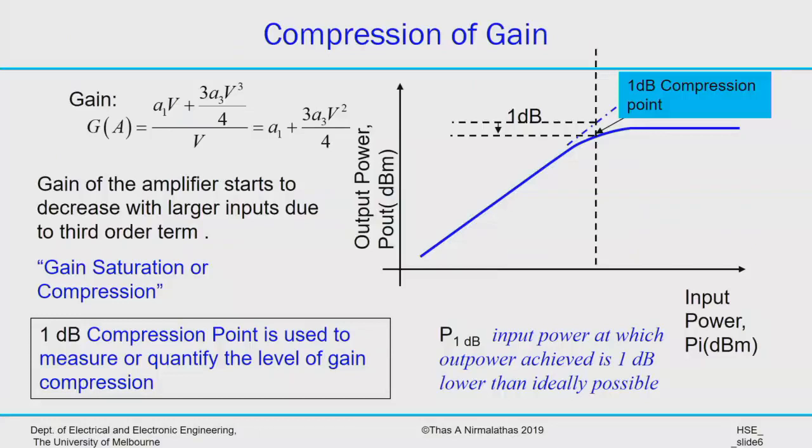So you can see there is immediately one problem. Even though you may have designed an amplifier with a gain that is supposed to remain constant according to your design, as I change the input signal it should produce a proportional output signal with the multiplier G that we wanted. With the one I've just shown you, once you have a third order nonlinearity inside that black box, your output gain is a function of the input voltage, and it goes up almost linearly up to some point, and then you can no longer keep amplifying it. The gain starts to saturate because of that term as a function of V squared on the top. So it is now becoming a function of input voltage rather than a constant.